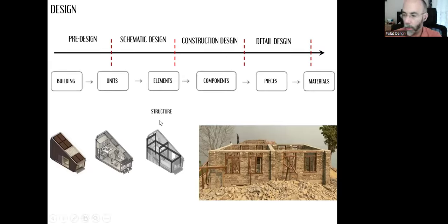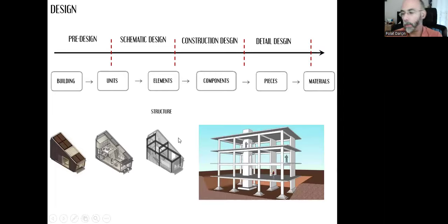If we want, of course, we can do a masonry structure, or if it's required, we can decide about a skeletal structure, and all these decisions can be made according to our previous decisions about the building form, about the context, like the ground properties, like the earthquake risk, all the possible loads that can affect the building and we can have, of course, structural engineer opinions and make the final decision.